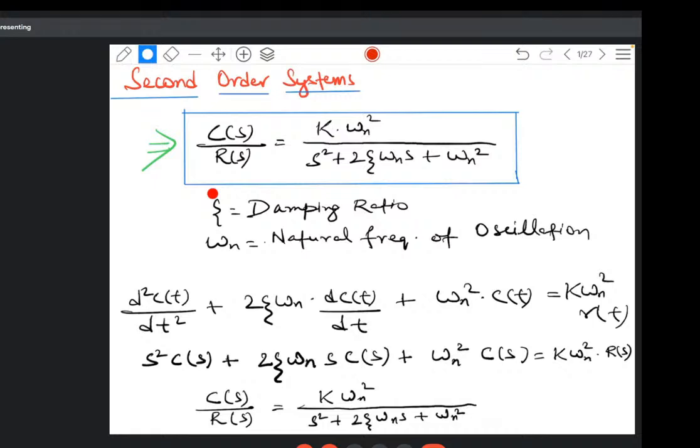So I need to damp out the oscillation or the vibration that is present in the system. Once I damp out or eliminate that oscillation, then definitely my response, after a certain period of oscillation, will come to its steady state, right? That is why we use the term zeta, because zeta is very significant here: that term represents how much the response oscillation is getting damped out.